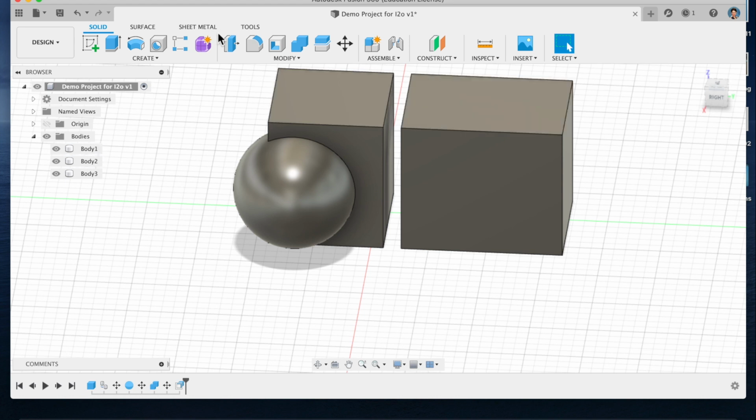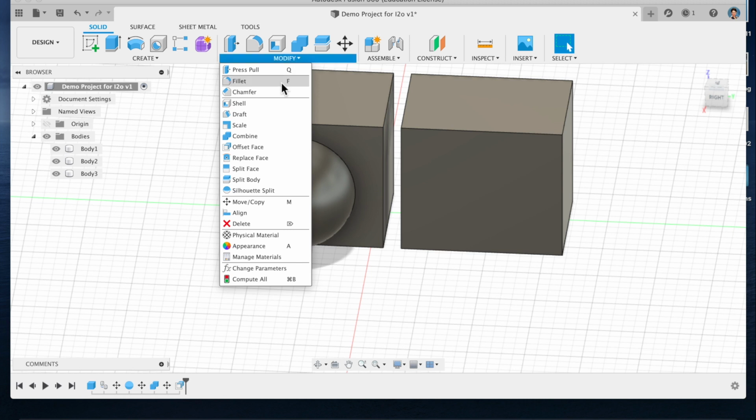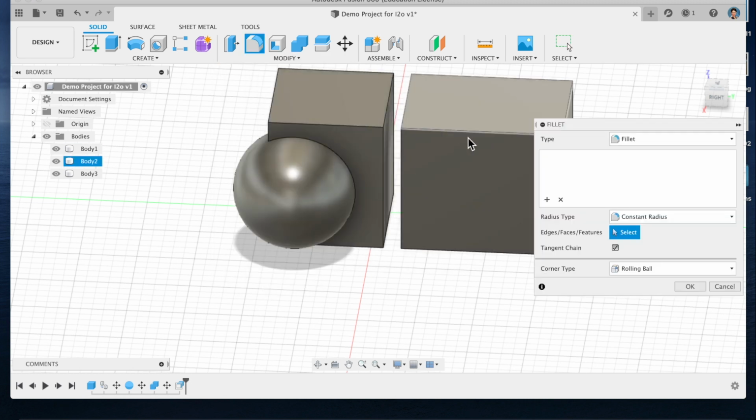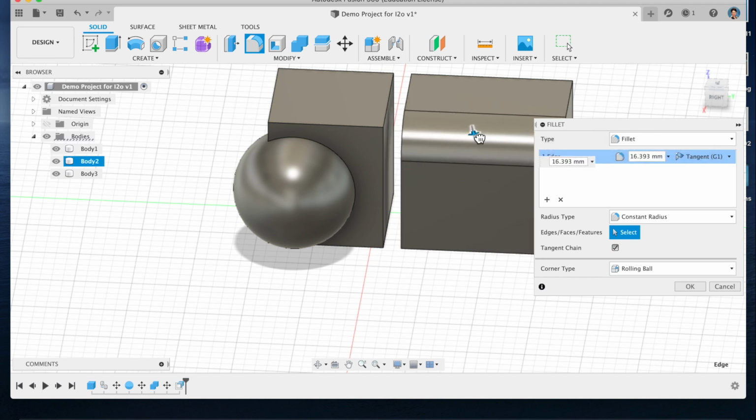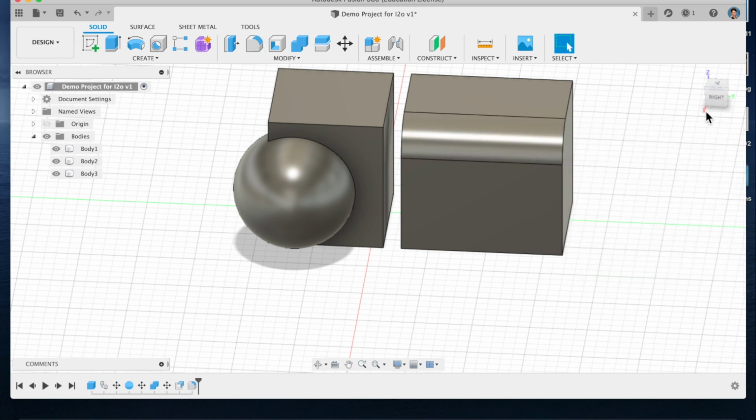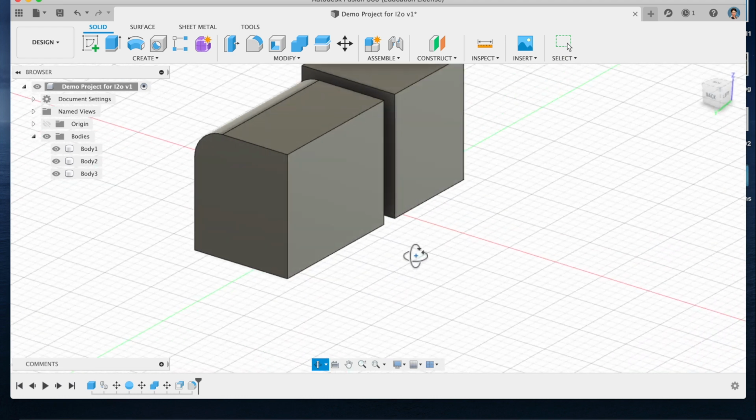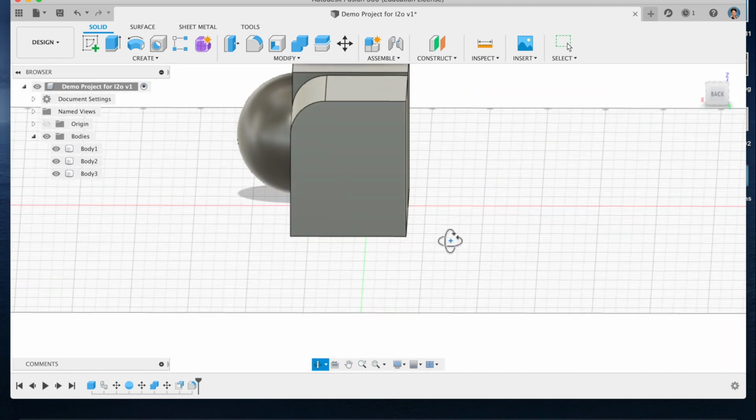Then what else do we need? We need, okay, fillet and chamfer. Fillet, also F key. You can fillet a corner and round it. It's very cool. You can also type in the radius for that. So if you know you want a nice round, say 15. Hello. You gonna let me do 15? Yes, thank you. Hit return. And then what does that look like? That looks like that. Oh, adorbs.